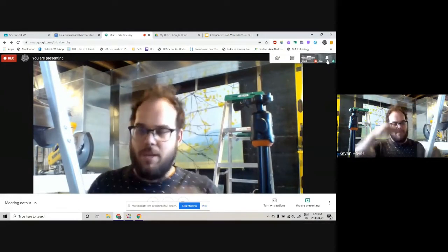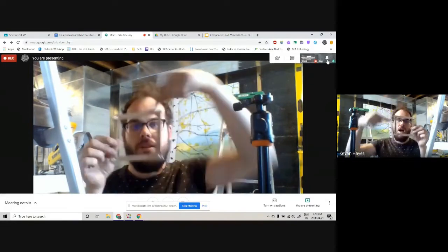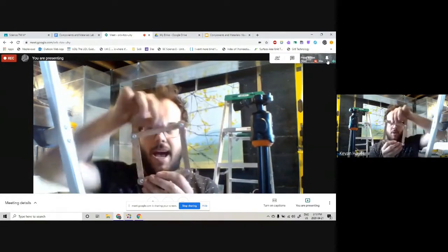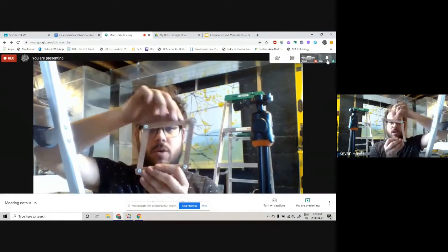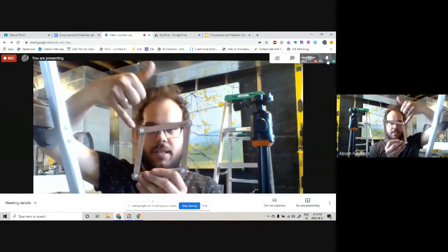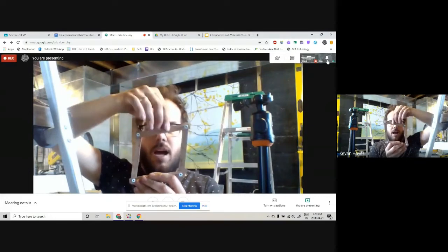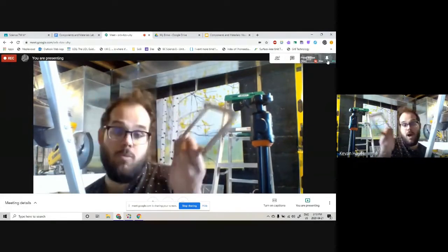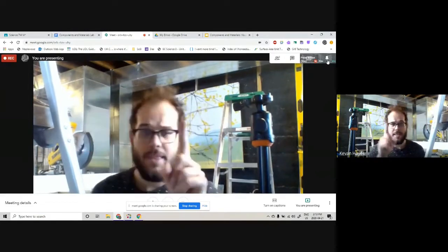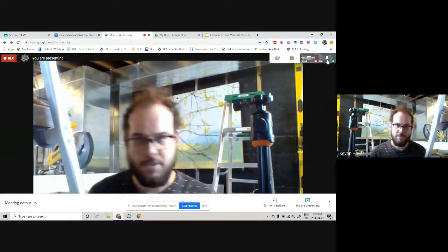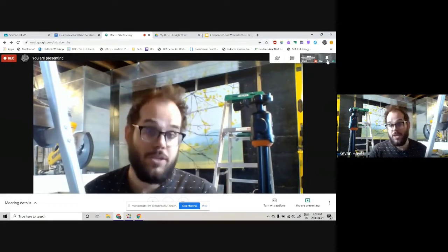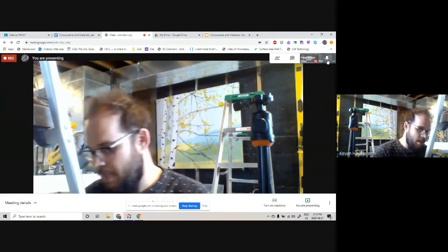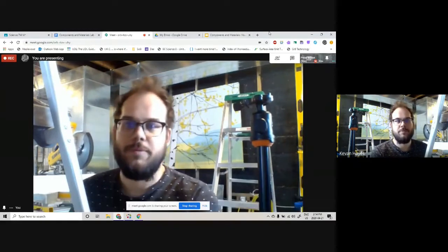You can try applying forces in different places, from the top, from the side, from the corners, and then start to think about how these structures fail. Is it the members that fail? Is it the joints that fail? If you apply too much force, what is it that breaks first and why? That's experiment number one. You'll just take some observations and play around with different shapes and how they produce different strength. Experiment number two.